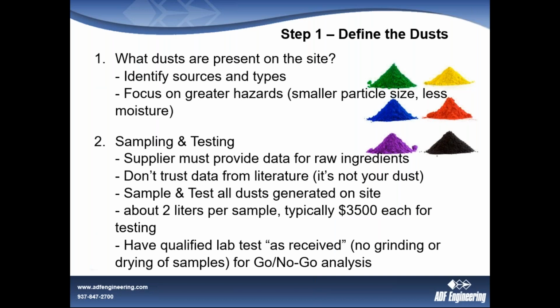So first of all, define your dusts. Not all dusts are the same, and you need to identify all of those different sources and different types, focus on the greater hazards. Okay, a greater hazard will come from a smaller particle size and a drier material.